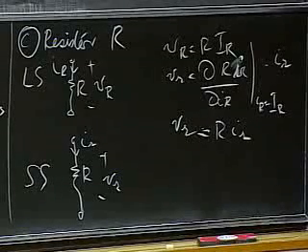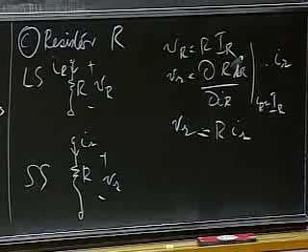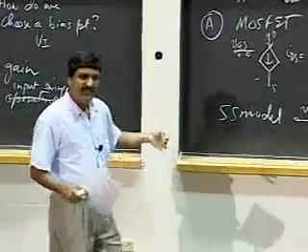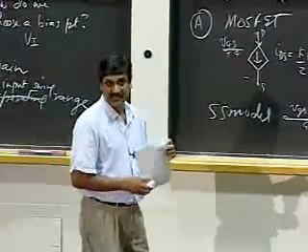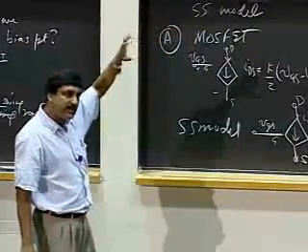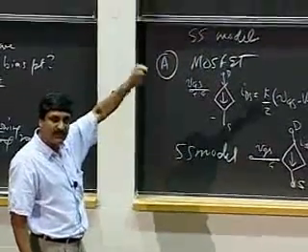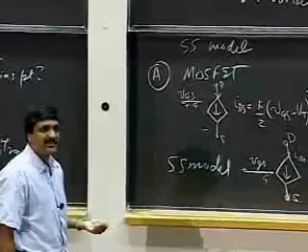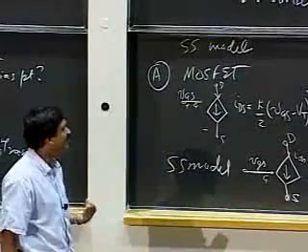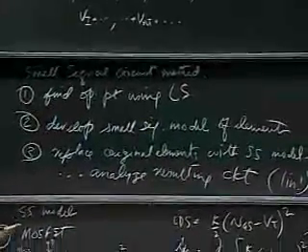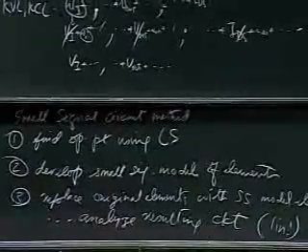So what I've done so far, let me just take you through where we are right now, give you the big picture here. So I began by suggesting that I was looking to find an even simpler way to do small signal analysis. I gave you an informal proof to show that if I had small signal element models for all my elements, I could simply replace them in the circuit and then do a corresponding linear circuit analysis to get the result I'm looking for. So there are 3 steps to the method. And as a first step, we began by finding small signal models for each of our elements.